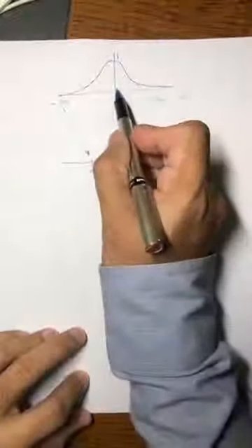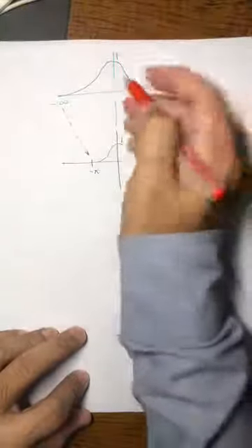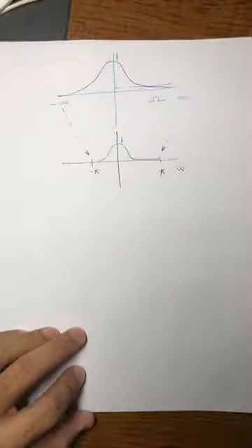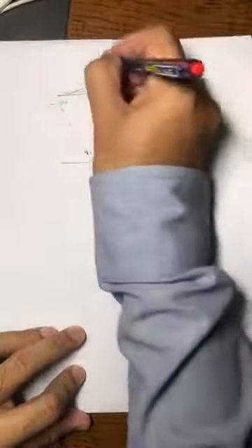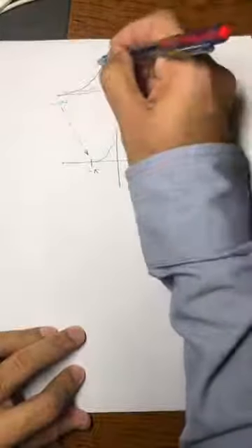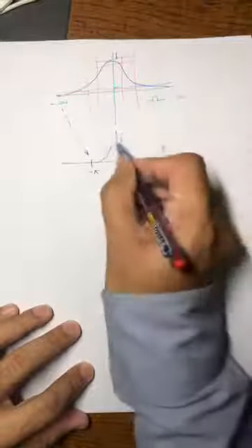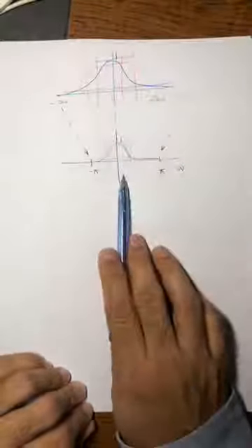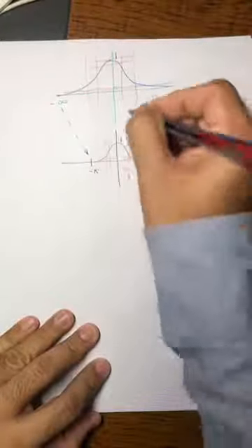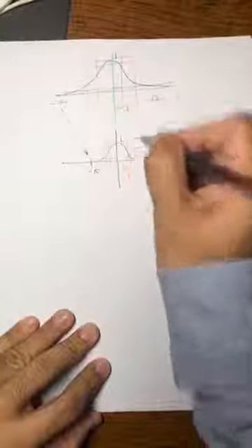so that if our analog filter is meeting these specifications, we can guarantee that our digital filter will also meet these specifications, only it will be just compressed. Okay, but I don't care, as long as it is meeting my pass band, stop band, and transition band specifications. I really don't mind if it changes its shape from this to this, because it is meeting my specification.